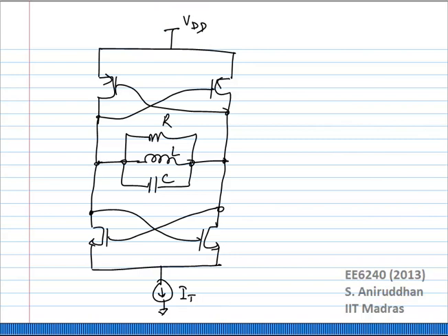So how do you analyze this circuit? In the previous case we said that the NMOS cross coupled pair has a strong positive feedback, current is switching on either side very quickly, right? Okay, what would you say about this case? Should be exactly the same, right? So you have these two NMOSFET switching, right? Depending on the waveforms on this side.